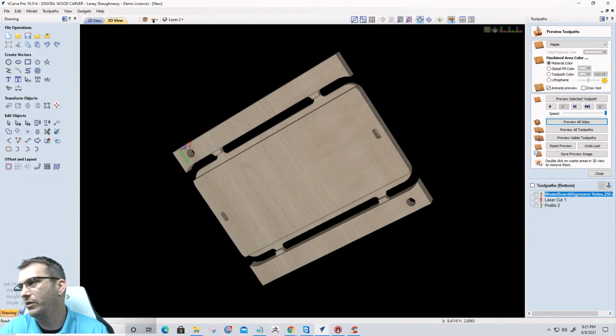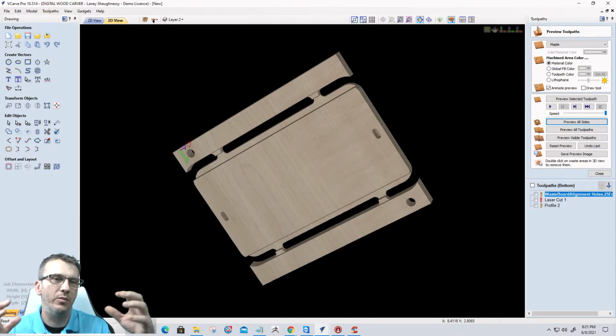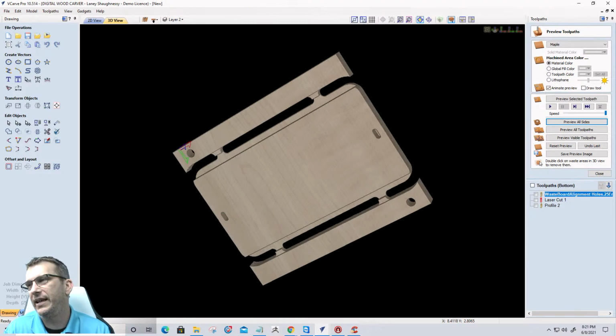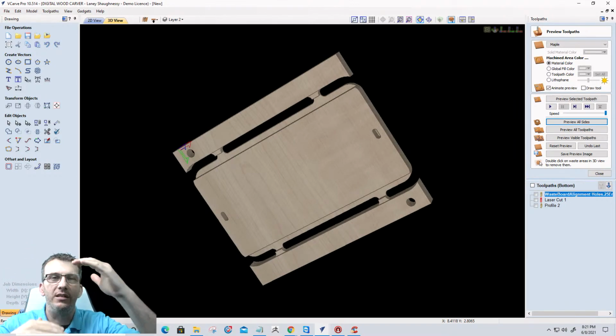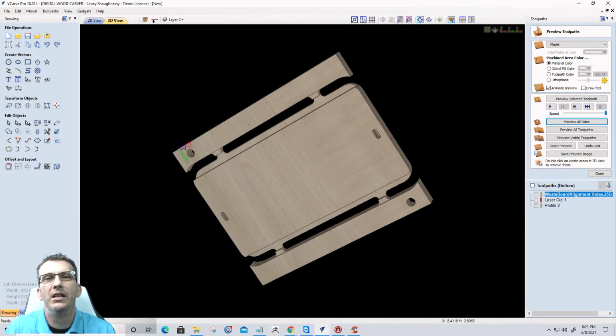You're going to need the add-on laser module for lasering 3D, especially with shading and highlighting your 3D models, because it's not going to be able to do it with a straight pocket, quick engrave, or profile. We need that pulse width modulation, so it shuts on and off, on and off, or it changes intensity, say 60 percent to 0 percent, 60 percent to 30 percent. So we need that modulation so we get those lighter and darker areas, those deeper and shallower areas. The laser module add-on provides that, where the regular toolpaths do not.